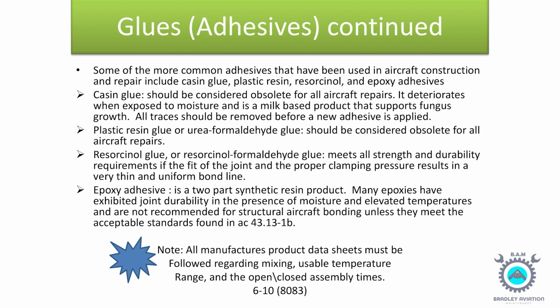Plastic resin glue, or urea formaldehyde glue, should be considered obsolete for all aircraft repairs. Resorcinol glue, or resorcinol formaldehyde glue, meets all strength and durability requirements if the fit of the joint and the proper clamping pressure result in a very thin and uniform bond line.